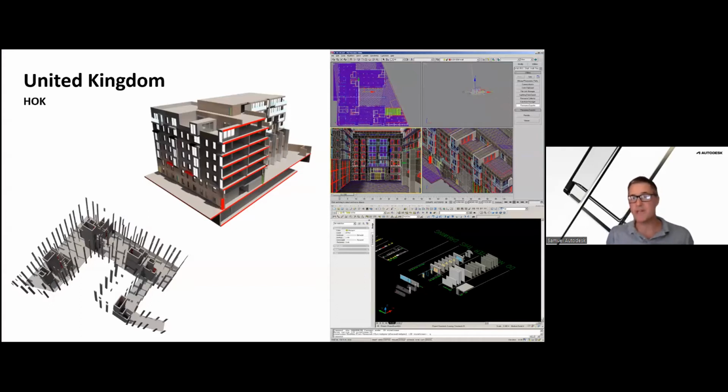This one was a project in the City of London, which involved the use of BIM to carefully work out the structure and the cores for a mixed-use residential. What is key here for anybody who has gone through designing structure and cores is the model had to displace a lot of loads over existing building components, and then we had to twist the cores to get the fire egress to work. So 3D modeling really helped this design process.